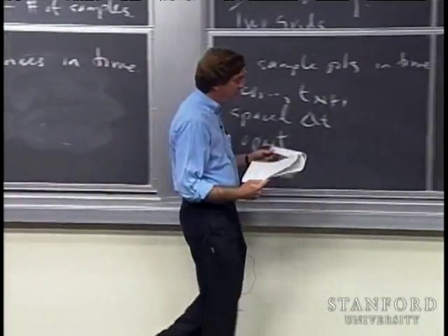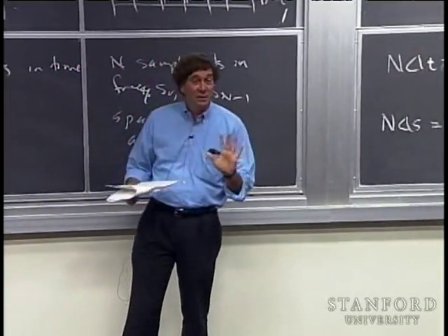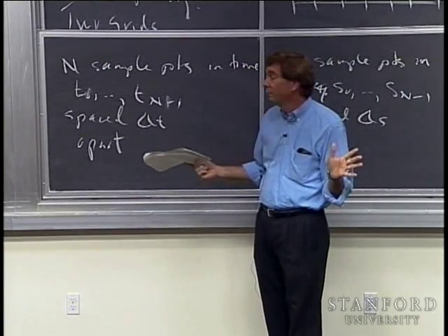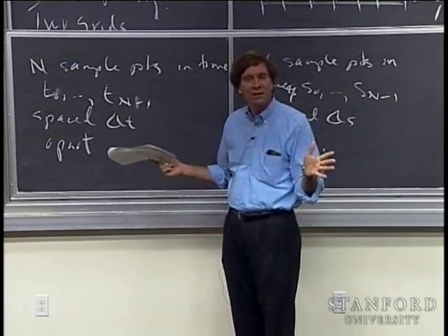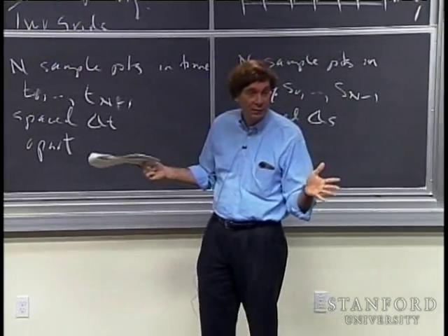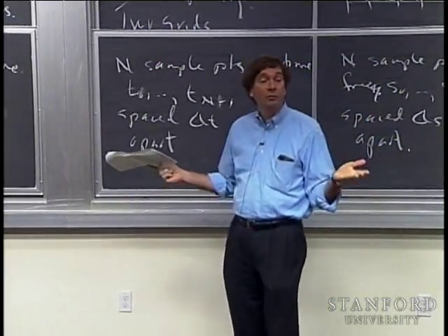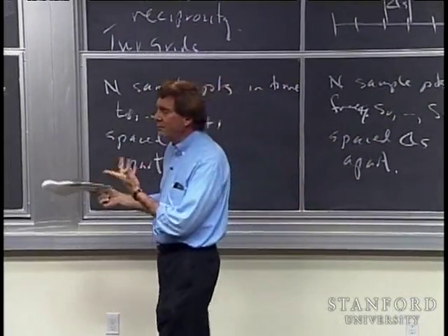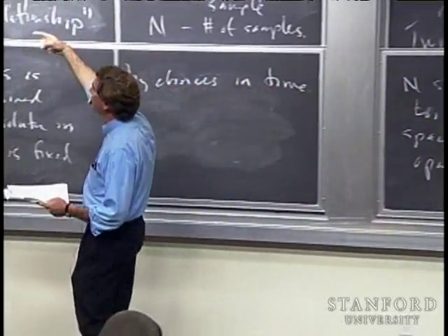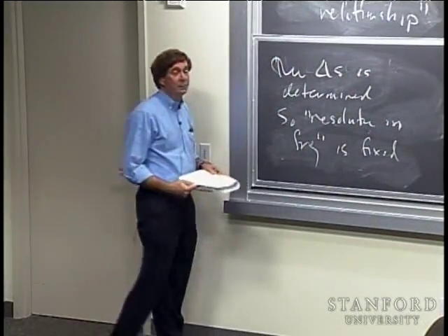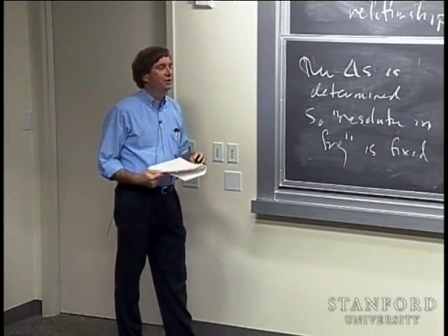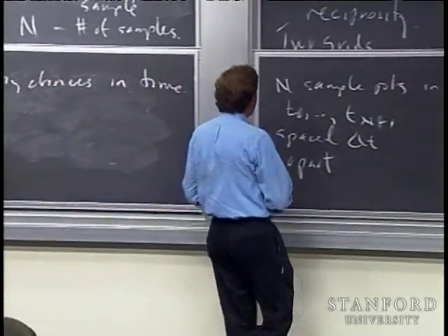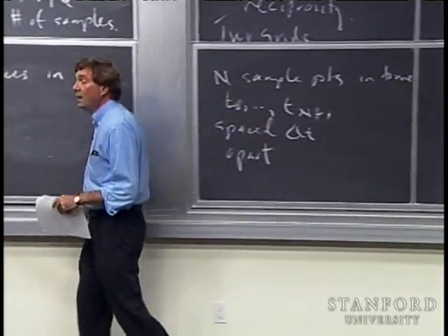All right, so I wanted to say that because it is the sort of thing that you meet, and you have to understand when you actually apply the DFT in most common contexts where it's associated somehow with some continuous process that you're sampling. You want to take the Fourier transform, you don't have a formula for it, you have to use numerical algorithms to actually compute it, and that means you're sampling, and the reciprocity relationship puts certain restrictions or limitations on what you should expect to get. Okay. All right, so that is my final nod, at least for now, back to the continuous case.